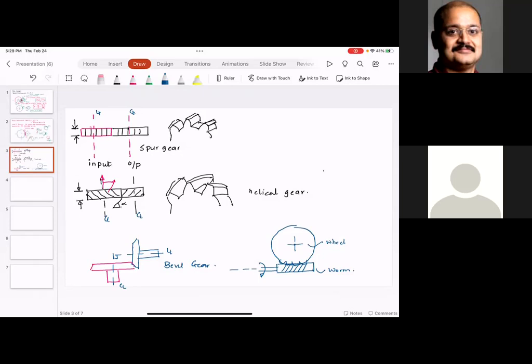When is it a good thing? Say, for example, the classic application of worm wheel is the hoist mechanism. Say this whole thing needs to lift people, and here there is a motor. And all of a sudden, power gets lost. No power to the motor. The wheel would get locked, so the load will not overrun under gravity. So typically in hoisting mechanisms, worm wheels are used.